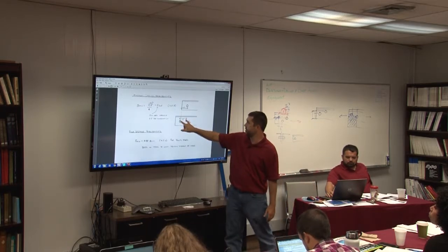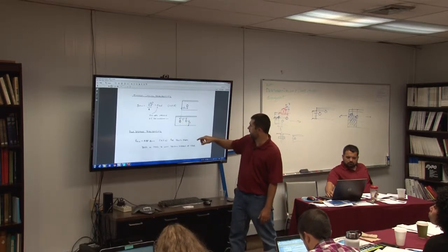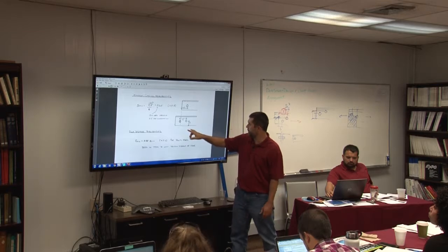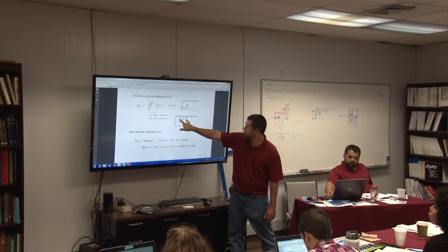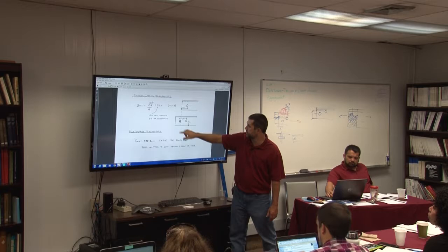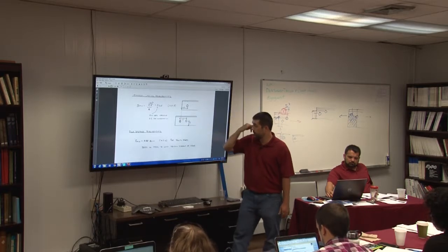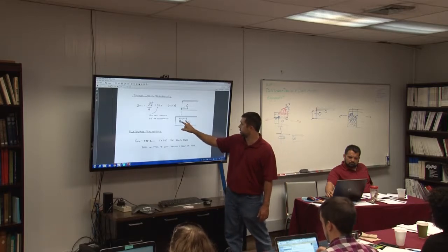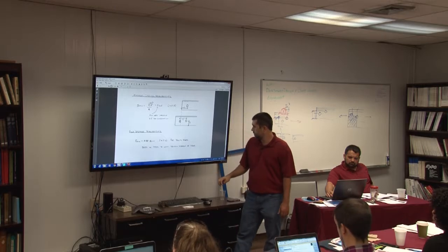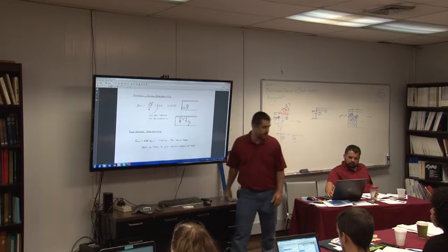You can do the same thing for spacing. It's just that I'm going to substitute, right? E is this value, and I'm going to substitute E for S, where I basically need to add 1/2 of a bolt diameter to get to kind of the equivalent spacing, right? And I don't have any data for the edge distance.